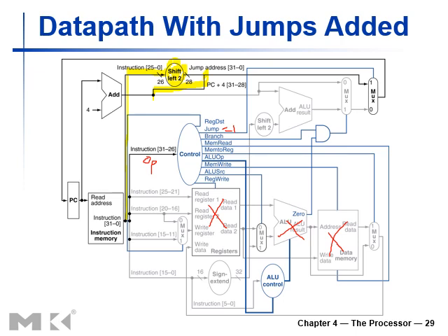So what we are doing is we are simply assigning the jump address's four most significant bits and connecting that with the program counter's four most significant bits. We are just making the interconnection. So this diagram doesn't mean that the whole PC plus 4, that is 32 bits, is concatenated with the jump address. We are only taking the most significant nibble here, and we are just replacing that with the jump address most significant 4 bits. So this is the jump address that is ready now.